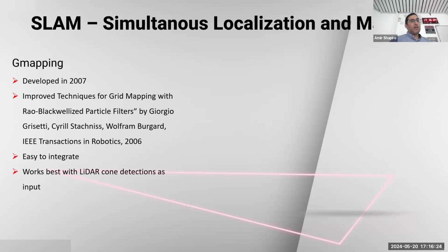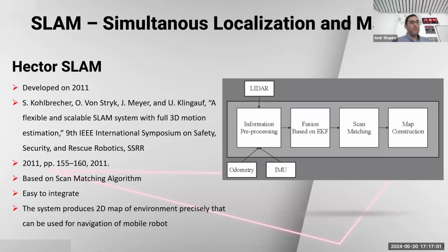The self-localization of the robot is done by odometry, by counting the rotation of the wheels and then calculating where the robot is, integrating this over time, and also a LiDAR to detect the obstacles and then map the environment. This worked okay, but not so good.